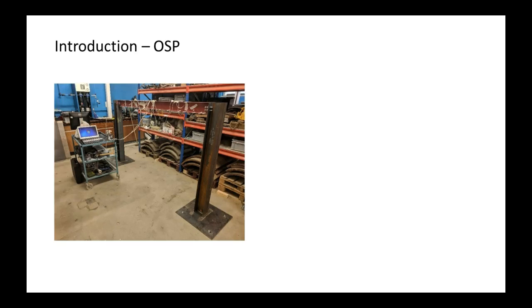So we are working on one of the projects where the aim is to identify the loosening of a few of the bolts, not all of the bolts, at the two ends of the steel beam. So this is a steel frame. In the steel frame there are 4 bolts here, 4 bolts here. If you loosen one or two of them, could you identify it using vibration signature? So that was the aim of the study here. Okay, so we can do that, but what to measure, where to measure? Those are the two questions that are raised.